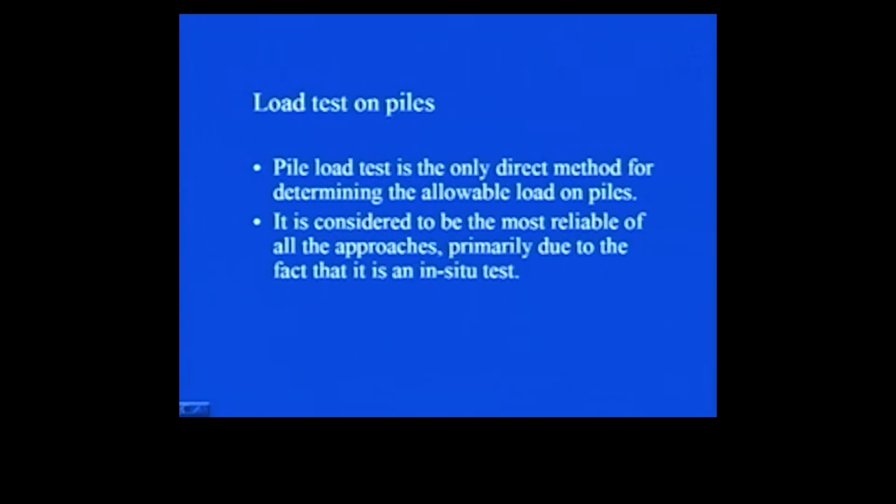In situ tests always represent the actual field condition. So, the reliability of an in situ test becomes more in that particular case, because if you simulate any particular case in the laboratory, first of all, all the conditions that you generate in the laboratory will be an assumption to the situation which exists in the field.